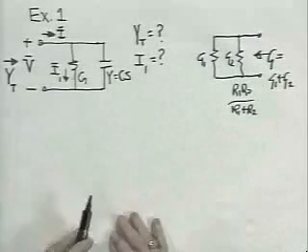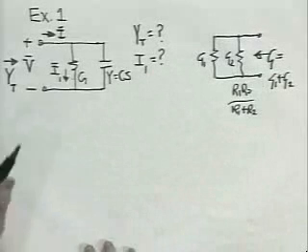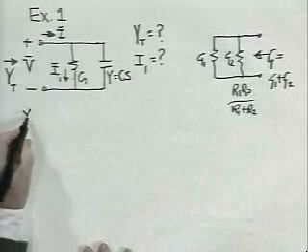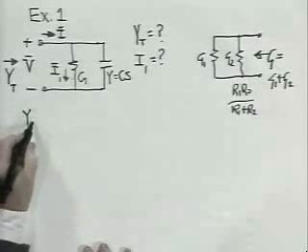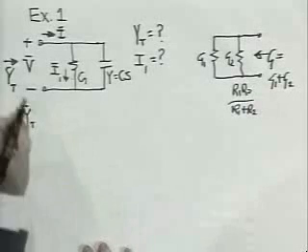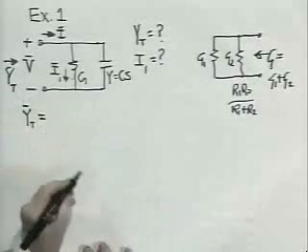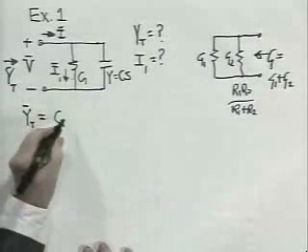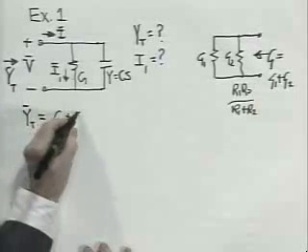Straightforward. Same story in networks with energy storage. The admittance, Y sub t, looking into this network, a complex number, is the sum of the two admittances. That is, it is G plus CS.